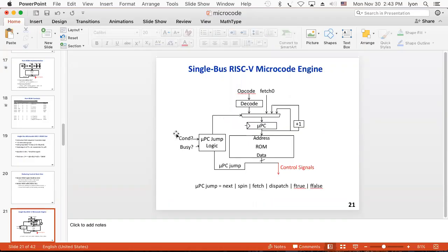This is a schematic depiction of the RISC-V block diagram micro engine. Here you can see he's doing a ROM lookup for what I'll call the jump controller that's embedded inside of the CPU. So the CPU becomes a finite state machine that effectively is programmed with ROM lookups.